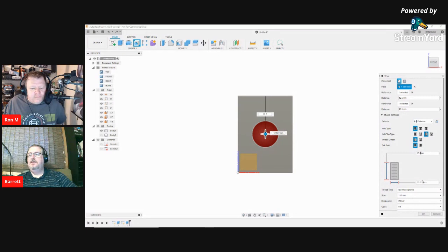Okay. So yeah, the size, now we are probably going to want to choose, it's automatically picking here for me a size of 12 millimeters, isometric. So M12 by 1.75, that's a realistic thread. Yeah. So right hand, you could change it to a left hand.